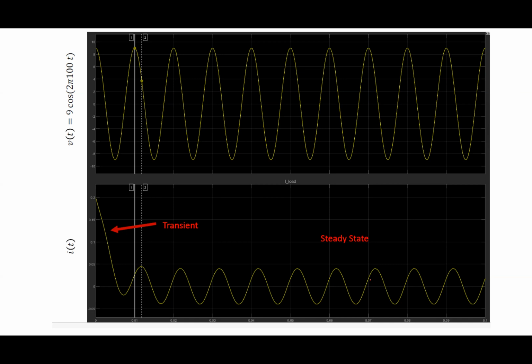So what happens if I take a hair dryer? What kind of circuit is a hair dryer? Basically a resistor. Yes, there are motors in it because there's air moving, but the big thing inside a hair dryer is the giant resistor that's heating up, and it's probably drawing 10 amps. When I pull that thing out of the wall, what happens? You get an arc. You see a flash of light.